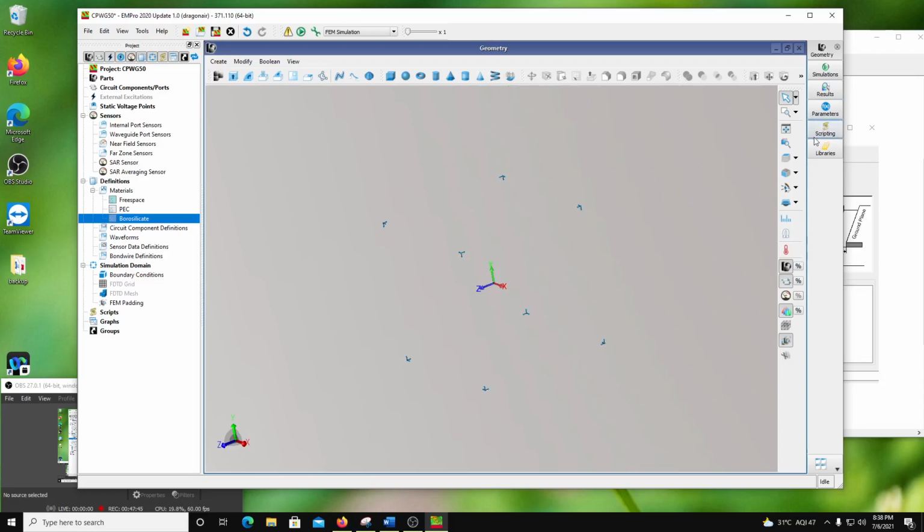All these primitives can be used for drawing, but you can always draw a 2D shape, just like in ADS, and then provide it an elevation. You can do a 2D drawing and then an elevation. We will see different forms of elevation with a certain draft, where you can make a cone or something like that. This is along the Z direction, so you take a 2D drawing and extrude it in the Z direction.